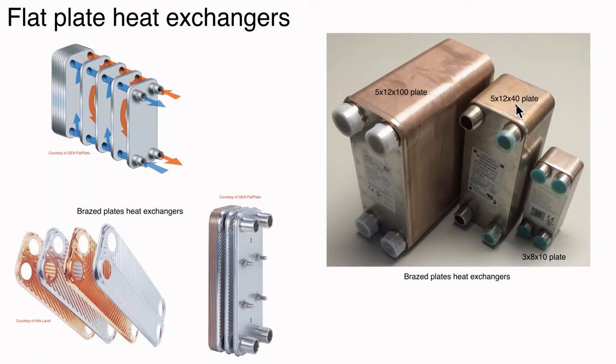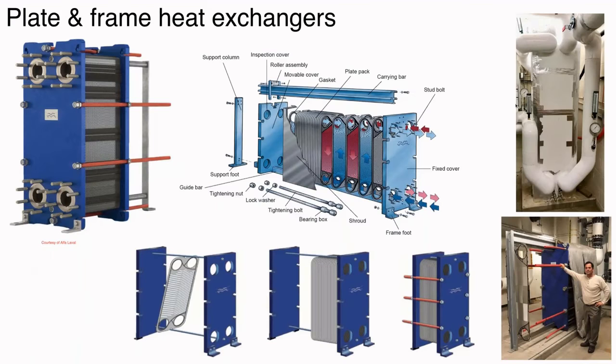And then finally, the little guy there, that's a 3 inch by 8 inch by 10 plate heat exchanger. And depending on what the water temperatures are or the fluid temperatures and flow rates, that small heat exchanger may be all you need. But be careful. One of the things you don't want to do is assume that a small heat exchanger will always do your heat transfer rates for you. Like anything else in hydronics, these need to be sized, and we'll talk about that.